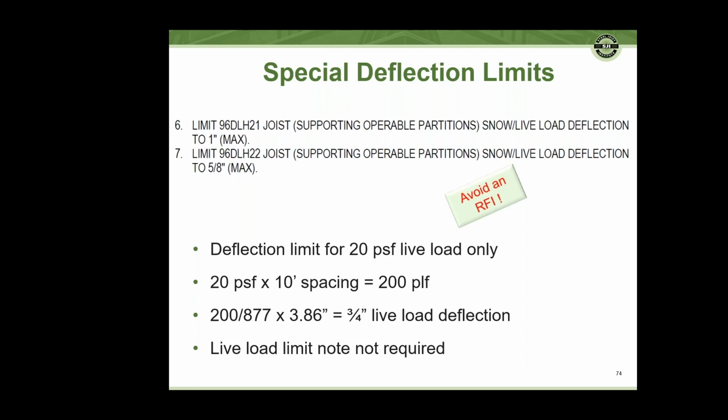Tim was talking about the tables and that red number being the live load. So that's a check the specifier can do and avoid the RFI. Or if you do have deflection live load limits, you still want the joist manufacturer to account for and check, it would be to provide the exact loading, live loading, or loading requirements that you would want checked for that condition.